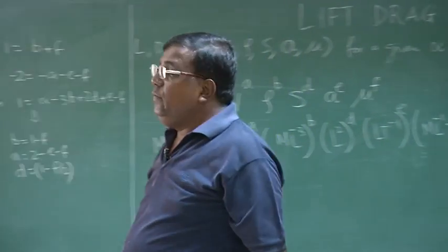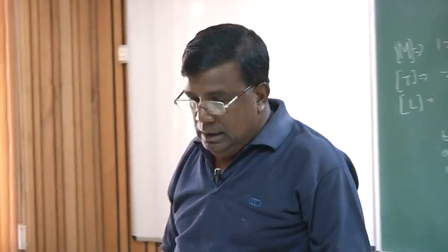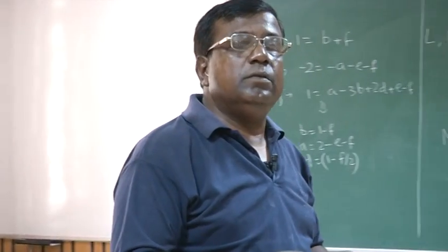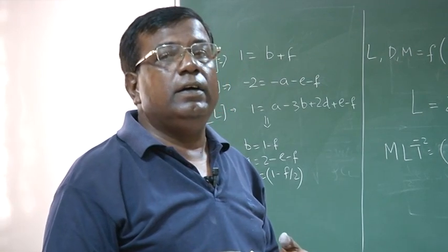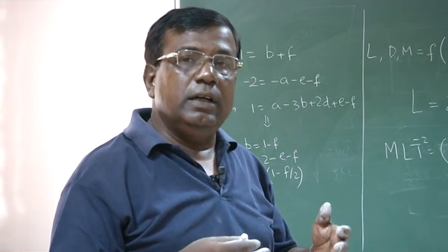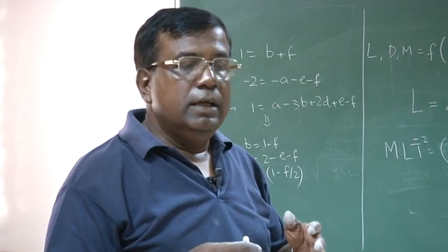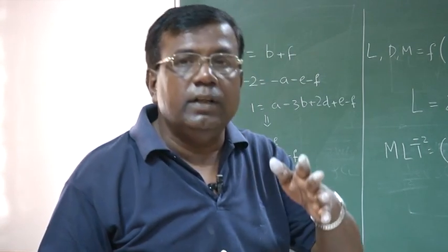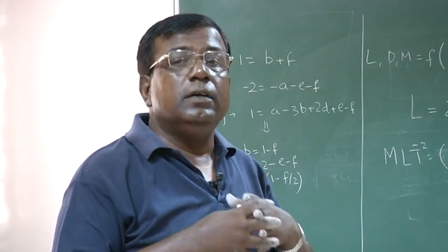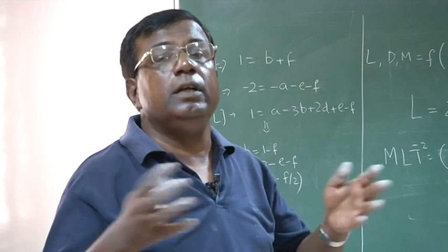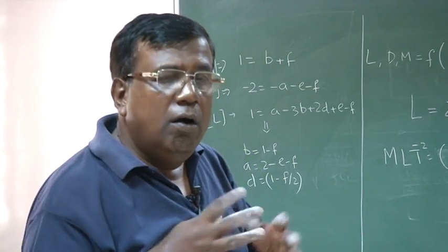The question now asked is, for a given alpha, taking into consideration the flow and the body interaction, what is that so-called complete description which will ensure that CL at a given alpha has been modeled accurately, keeping in mind there is a flow over the surface, there is a boundary layer, there is a viscous force, the viscous boundary layer will be redistributing the pressure distribution, all these things.